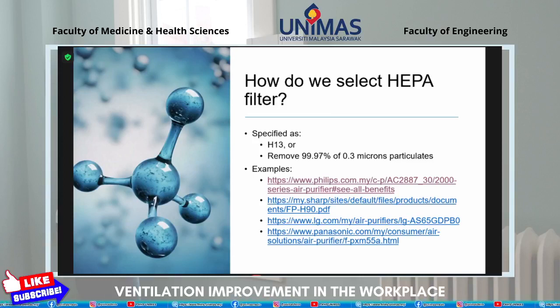But I don't see the effectiveness of that ionizer in removing the aerosol and also removing the viruses. So the only hope that we have in the air cleaner that is proven to remove the aerosol is the H13 HEPA filter, which is the lowest grade of the HEPA filter.